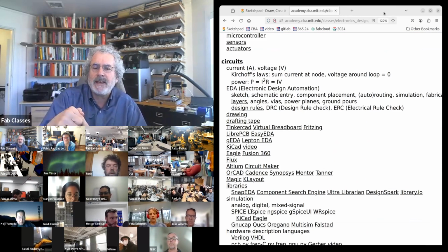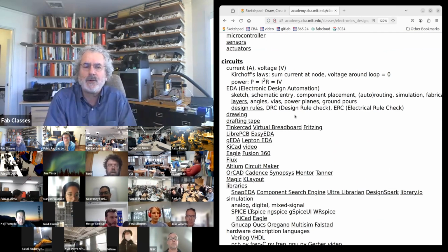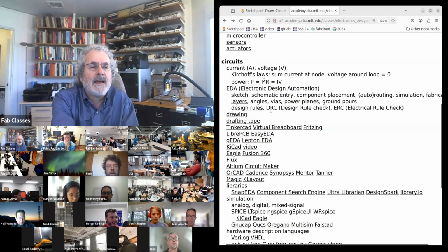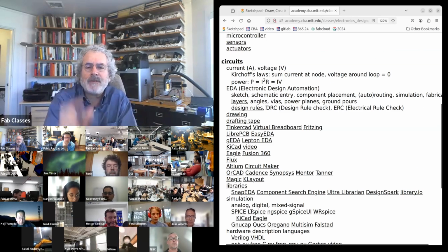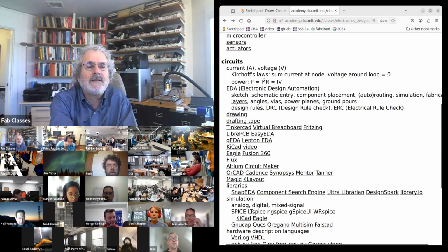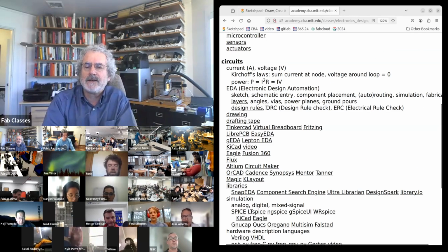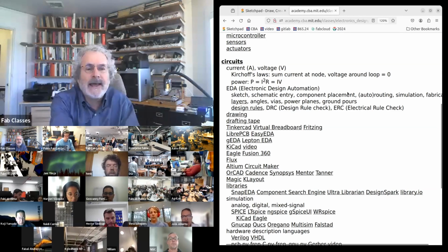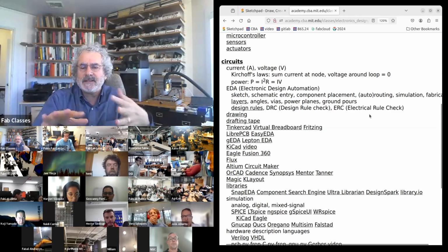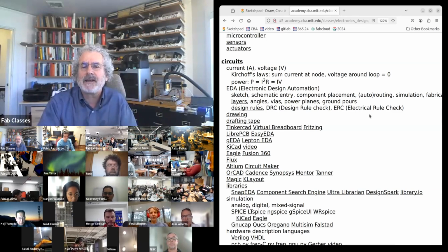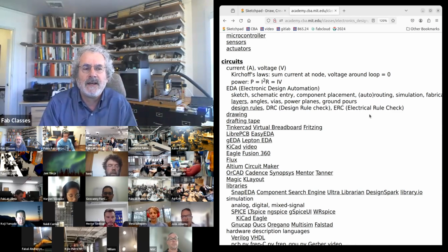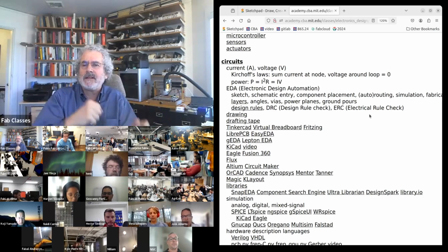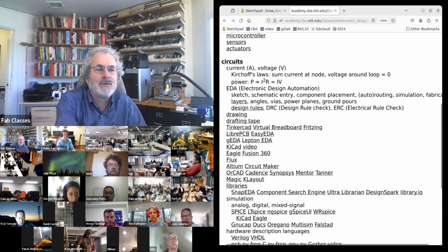Similarly, if you're going to fabricate it in-house, it's related to the tooling you're using. And so for a non-trivial board, you need to do a design rule check, which is, can you fabricate it? And you need to do an electrical rule check, which is, does the board actually reflect the circuit you designed? And so all of that is so specialized. That's where there are these tools.